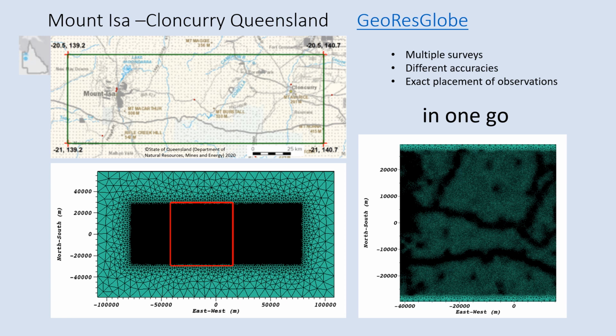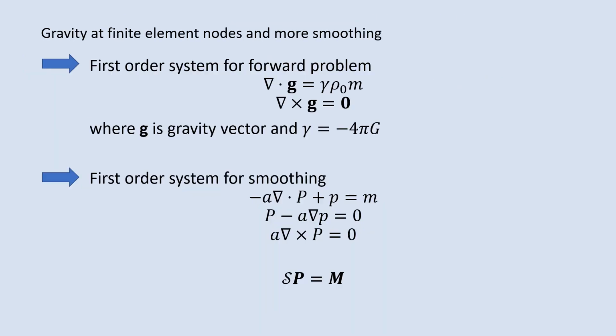I have shown the ground level mesh. It has a really coarse mesh in the buffer region and a very refined mesh around the observation points. I have shown a blow-up region, the red square, to show how mesh size varies at ground level. The observation spacings had a maximum of 2 kilometers and a minimum of 0.7 meters, so there was a significant difference in element sizes at ground level.